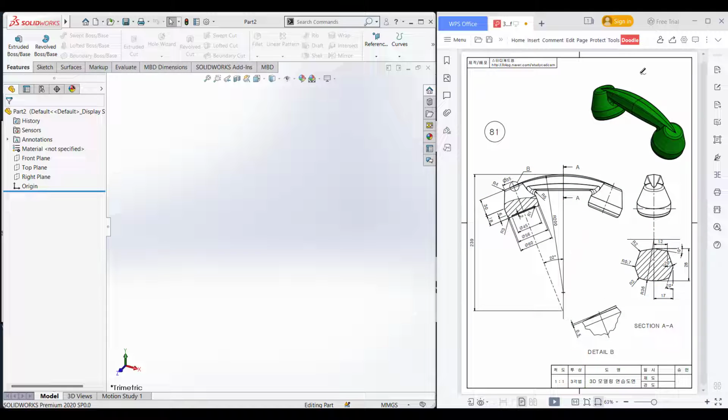First of all, I will start drawing this handle shape. For making this handle shape, I will use the loft boss feature. In the right plane, I will first draw this polygon, and after drawing this polygon, as we will use loft boss, we need another two closed shapes. So I will take a shape here and another shape here, and the middle section will be this shape.